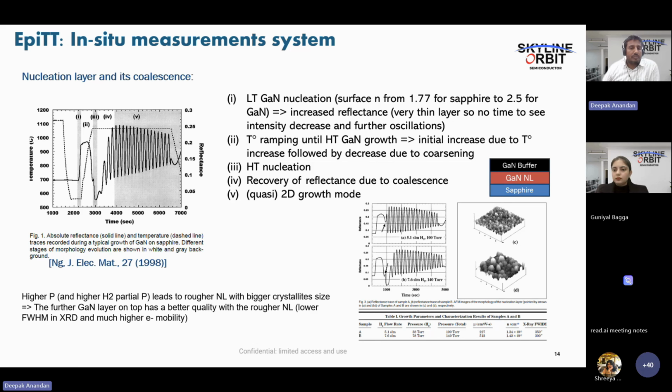So people are trying to control the VT variations and also the breakdown voltage with different techniques like passivation, silicon nitride based passivation, or in situ silicon nitride passivation. So reliability is still the major concern in gallium nitride, and people are trying to address it with different passivation techniques.